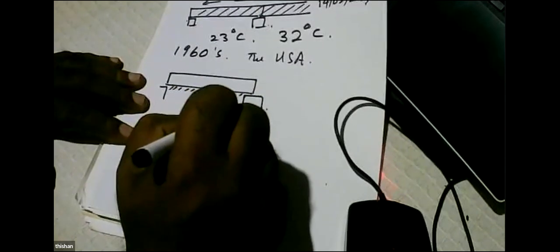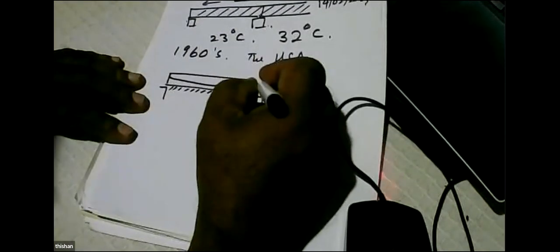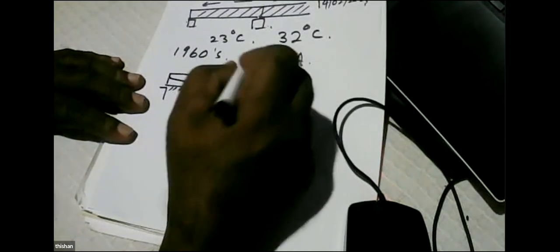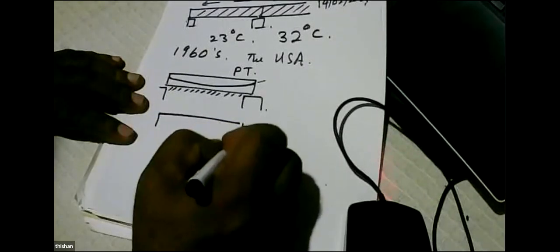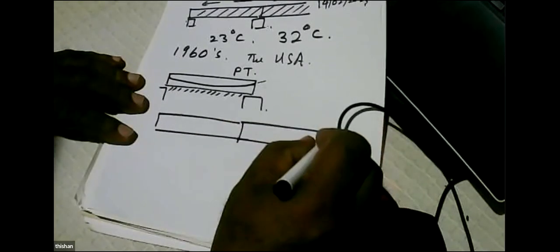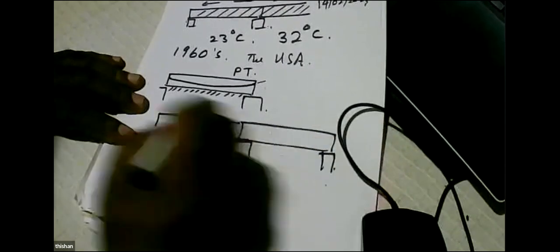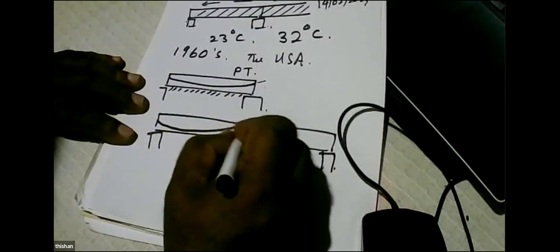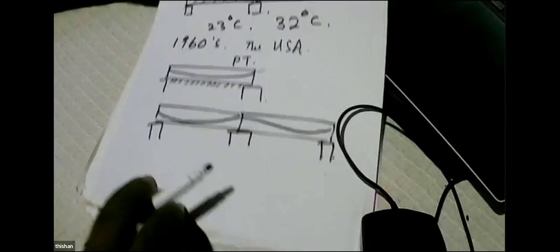So they found that, up to 20 meters, the easiest thing is to prepare some formwork and pour concrete. Before pouring, you will just have some pre-stress tendons, and after pouring, you will stress them, and it will make it a PT post-tension bridge. And sometimes they even had 2 spans done in one go, so you would have pre-stressing tendons like this.